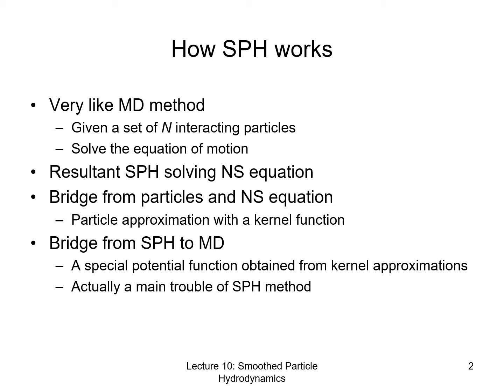Why does SPH use particles? They are solving the Navier-Stokes equations, and molecular dynamics uses particles but solves a microscopic dynamics. The difference is that for the SPH method, there is one bridge built between the particles and the Navier-Stokes equations.